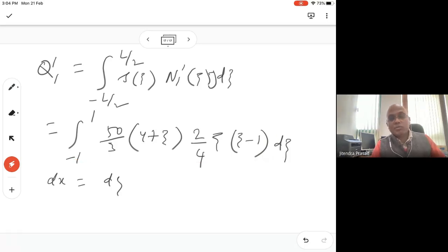The main thing is it is the same as earlier, only S is a function of x, and here the bottom line is S has to be converted into the xi system. The shape function and S function have to follow the same coordinate system, otherwise there will be a problem. That's the takeaway.